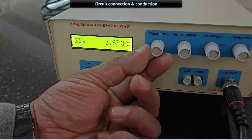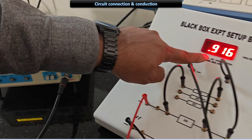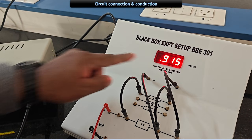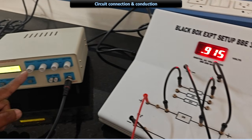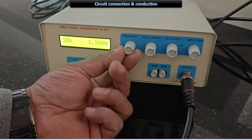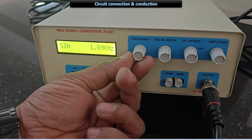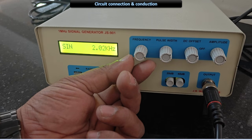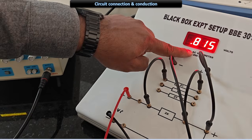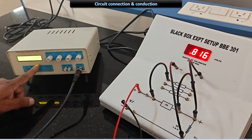And take the respective voltmeter reading, that is the voltage gain, 0.914 in this case. Once you are done with this, again go back to the frequency knob and keep it at 2 kilohertz. The respective voltage gain should be noted down, and repeat this up to 10 kilohertz, in steps of 1 kilohertz. From 1, 2, 3, 4 up, you have to go up to 10 kilohertz.